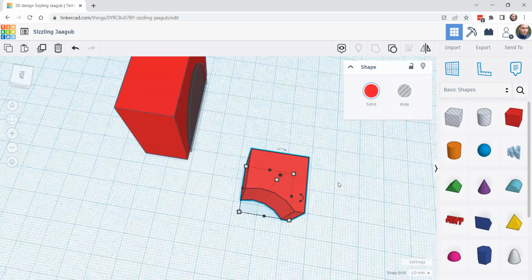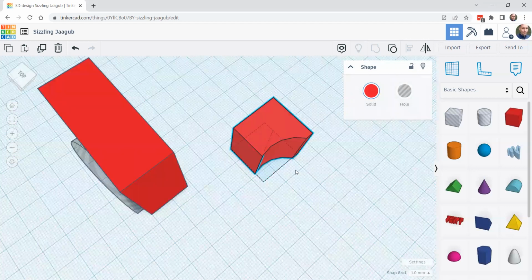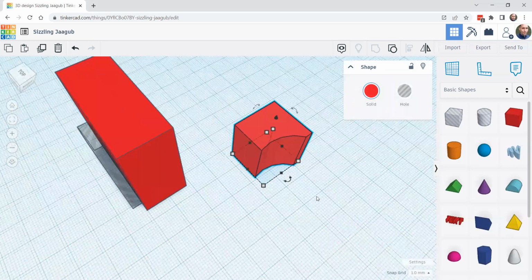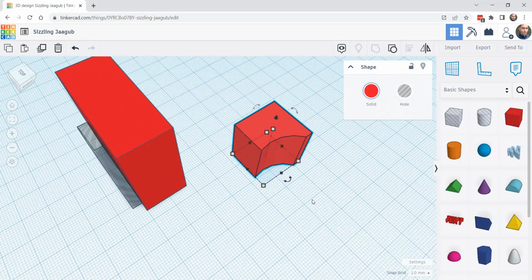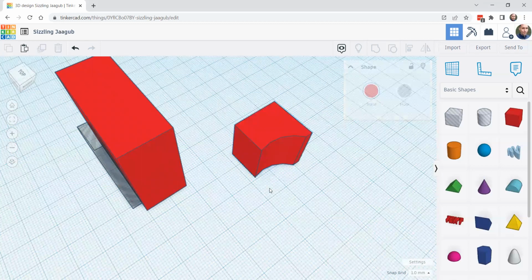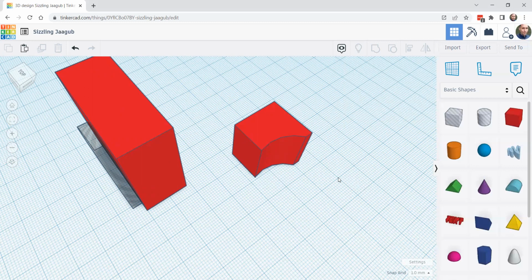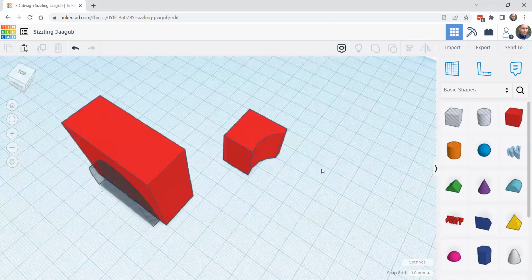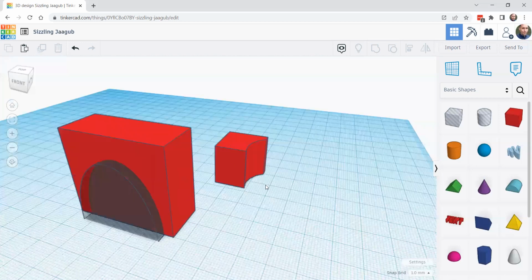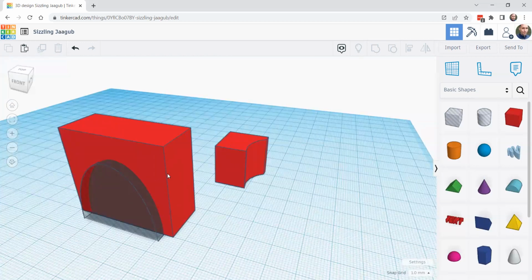And this is really one of the most powerful tools and easiest to use once you get used to it in Tinkercad, because it lets you combine shapes as both positive elements or negative elements, to add or subtract elements of your actual objects. And we're going to be using that a lot in our different examples throughout the course. It's definitely one of the handiest and easiest ways to take a basic shape and make it a little bit more interesting, more unique and dynamic.